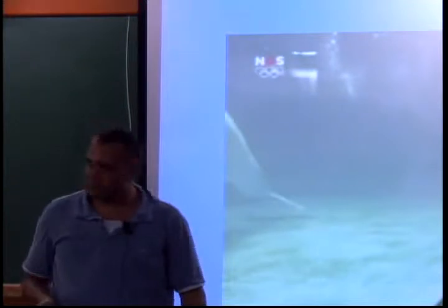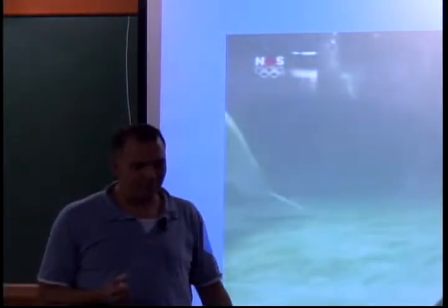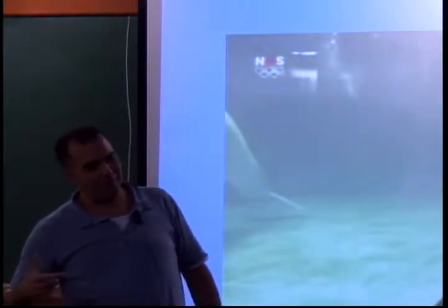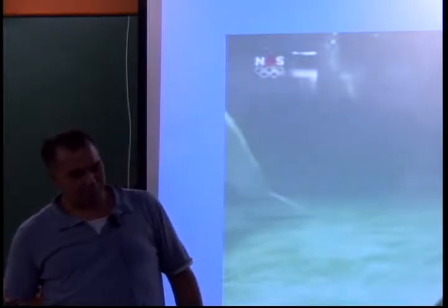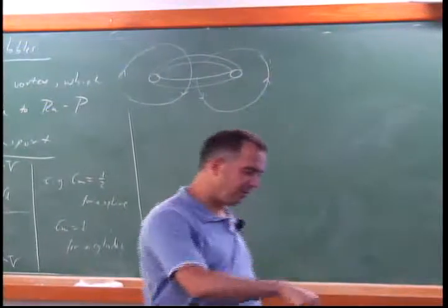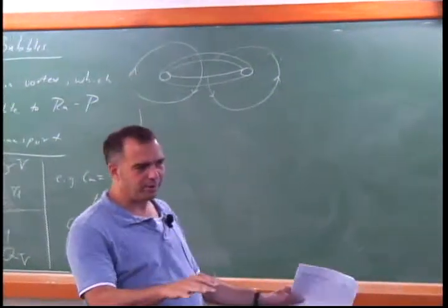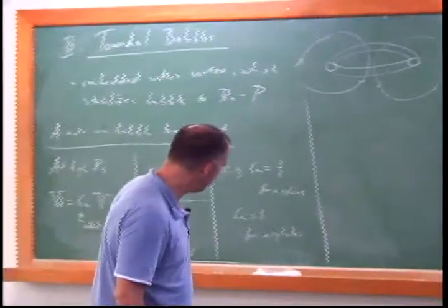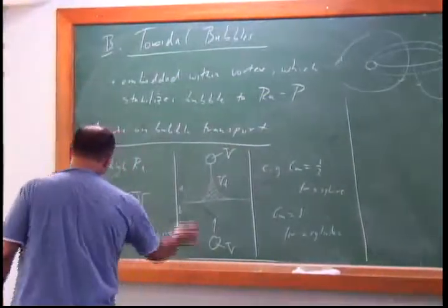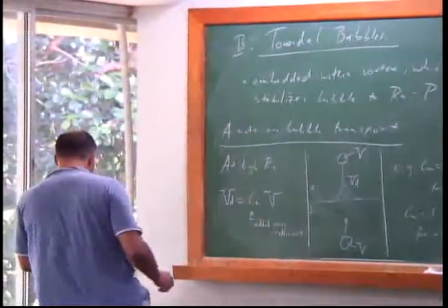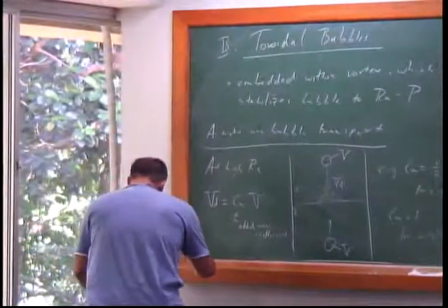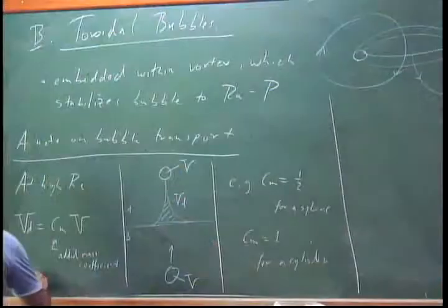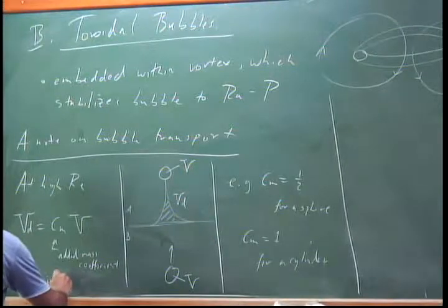It's not always important. So when is added mass important? Added mass is important when the kinetic energy of the surrounding fluid is comparable or larger than the kinetic energy of the object. So if you have a cannonball, for example, going into water, you don't have to worry about added mass, but you do have to worry about it in bubble situations. But it's just sort of funny that it comes up here. And this was done, again, by Darwin, who is the grandson of Charles Darwin.